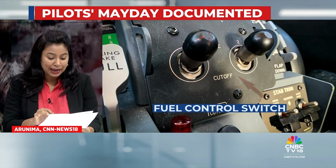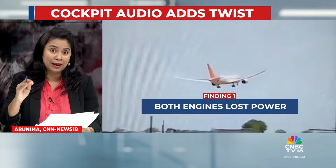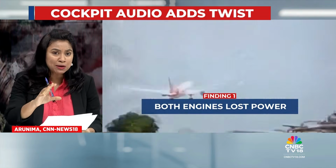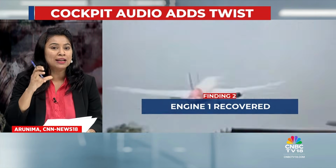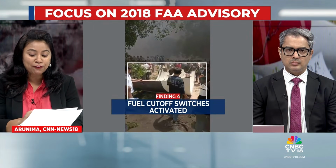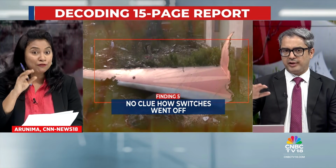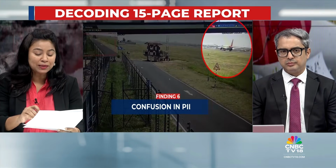By 8:08:42, it has hit the maximum speed, which means that till this point the engine has enough power, which makes me conclude that the fuel switch is in its run position, and fuel is still going to the engine. What happened then suddenly at 8:08:56? This is when pilots realize that there's something wrong. But 8:08:56 is after takeoff. Yes, 8:08:42 is when the maximum speed has been achieved, which means they have taken off.